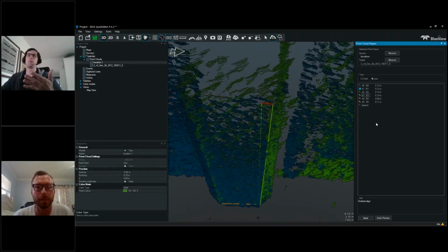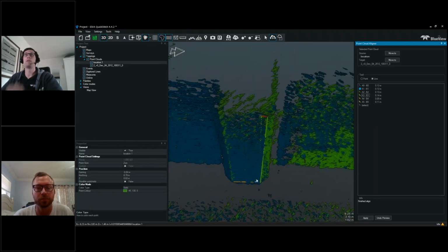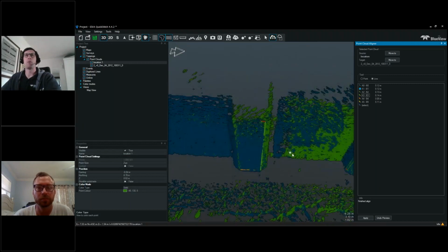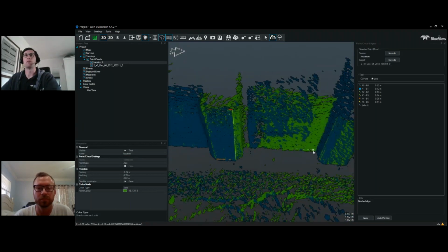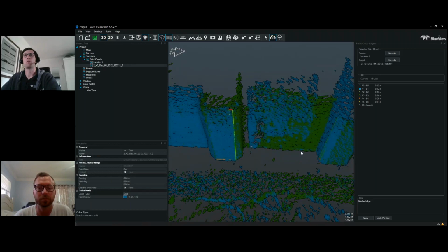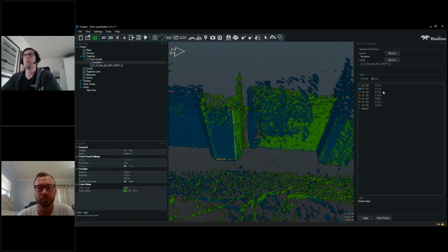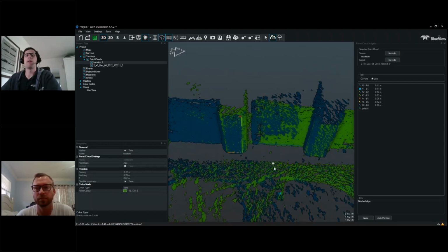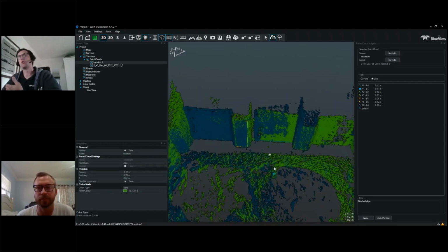And you might get a better result by removing a bad pair, or even re-designating a pair, so redrawing it. Maybe you just didn't have it on that outer corner. If I were to remove it and redraw it, I might have a much better result. You can add more pairs in real time here as needed. So if I were to do another one here, it just added another pair. Did it improve my result? Maybe a bit actually, but you can add them and have it calculate the registration in real time with each additional pair you add.